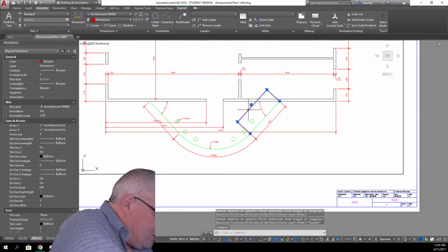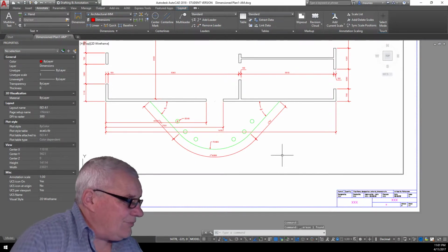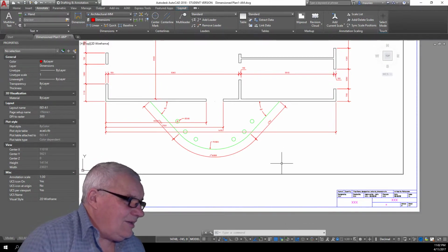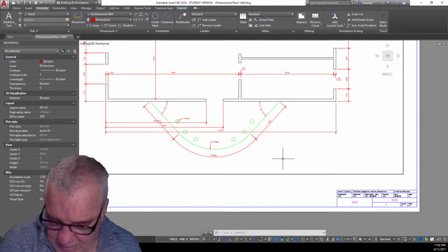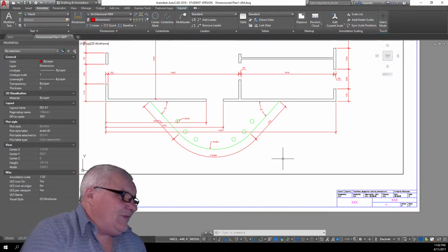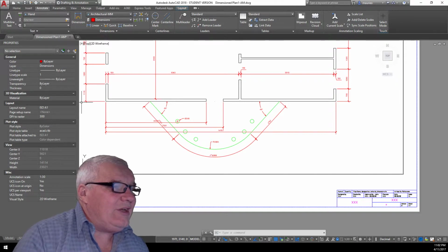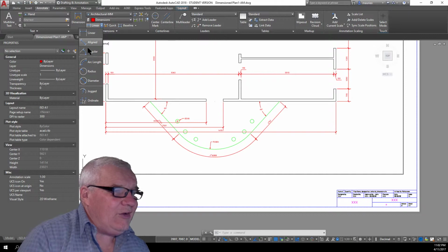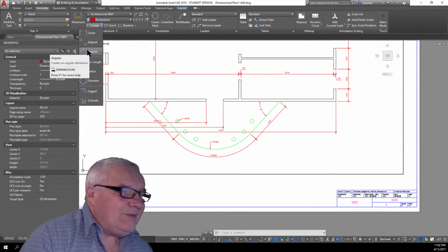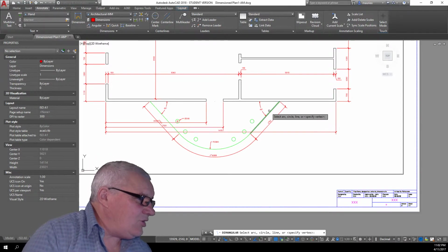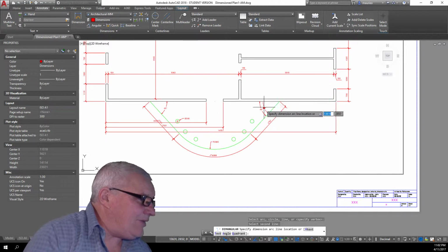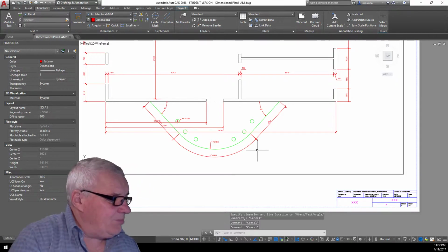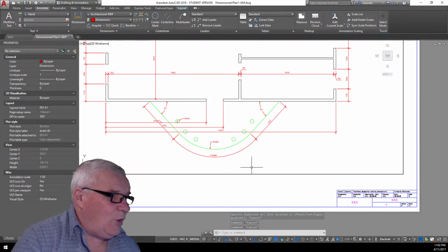I'm going to delete that one there. So I managed to get my angle after first doing a distance. So again, there's a little bit of fiddliness going on by just doing that dimension. There are other ways of doing the angle line. You can just go here with angular, click on this one here, and you can just go bang bang, and that'll give you your angle, which possibly I find a little quicker.